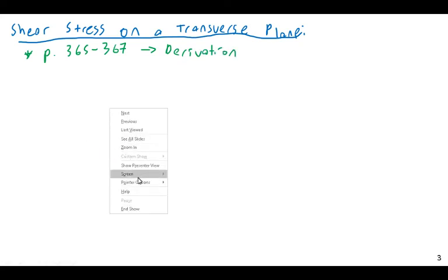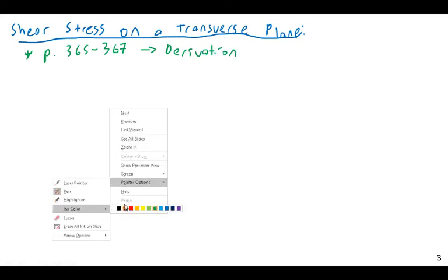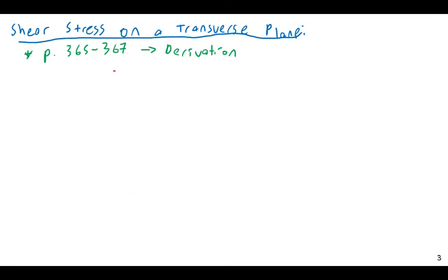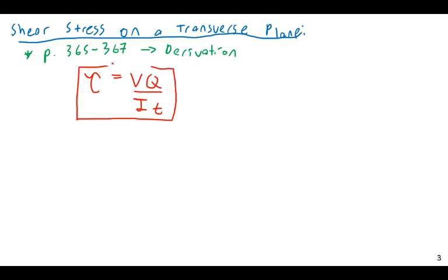Okay, and the formula for shear stress, this is going to be interesting. You'll see a quantity that we haven't seen before that we will learn how to calculate. Well, actually, you've probably seen it before. It's not that bad. Tau equals VQ over It. Wow, doesn't this look like fun? Tau equals VQ over It. Aren't you just giddy at figuring out what all these fun terms mean?